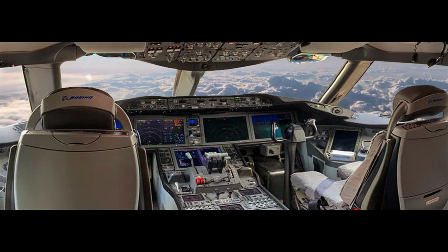4. Possible malfunction. If at any time the pilot observes unexpected or uncommanded behavior from the autopilot, he or she should disengage the autopilot until determination of the cause and its resolution. Most autopilot systems have multiple methods of disengagement. You should be immediately aware of all of them. Also be aware of the methods to cancel the FD display to avoid confusing information.